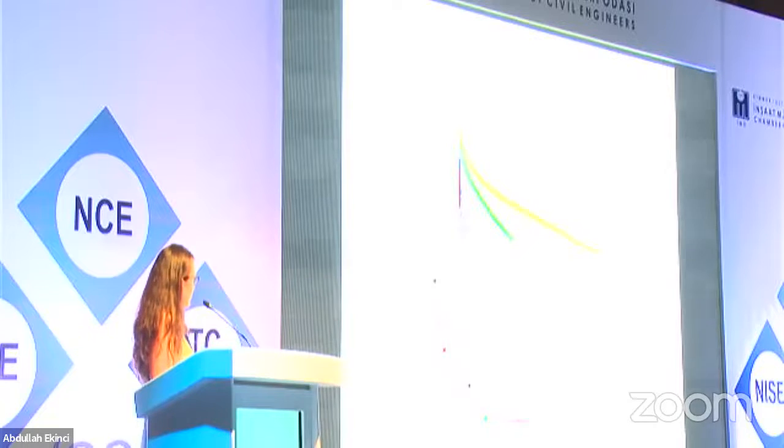Now, to quantify this dependency, we can also plot this data in a similar rate of representation, and obviously the dependency now becomes linear and can be approximated using a linear regression. The quantification of this dependency can be expressed by the regression coefficient, the KL value here, and considering some reference value of the initial relative density, we are also able to find a reference value of the rate of pore water pressure corresponding to this reference value of the initial relative density.